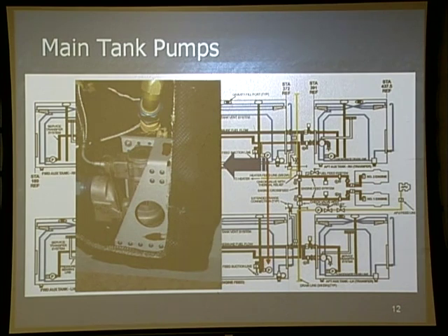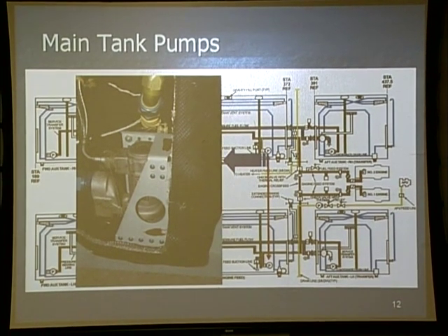Now, the main pumps, are they required for flight? Are the main pumps required for flight? Okay, I got one nodding yes. Below 6,000 feet. What? Below 6,000. At below 6,000 feet, they are required. Excuse me. Above 6,000 feet, they are required. Below 6,000 feet, they are not required. The engine-driven fuel pumps will suck fuel out of those main tanks just fine.